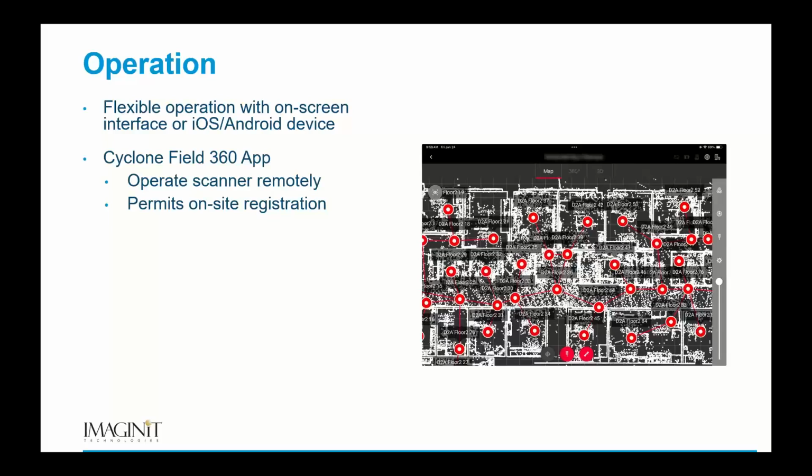Case in point, I was on a job site with a customer doing a presentation, and they said, we want to go to this area. So we did this area, and they said, we need to jump over here, and then we want to come back because we want to test the Viz system and how good it works. So we jumped from one side of the building to the other, about 2.5 minutes to walk. We scanned it, worked our way back a couple scans. The Viz kept track of where we were, and all of that shows on the iPad. I was able to register all that data together without manually doing extra scans. It knew where I was, and we worked back, all registered together within 1/8 of an inch.